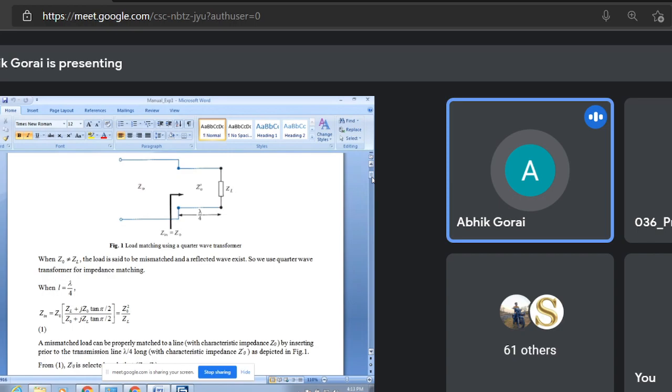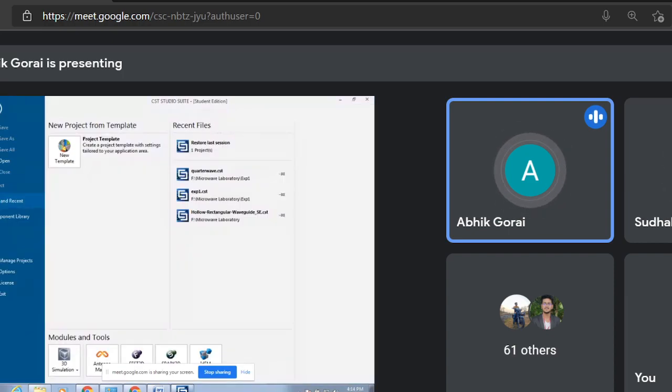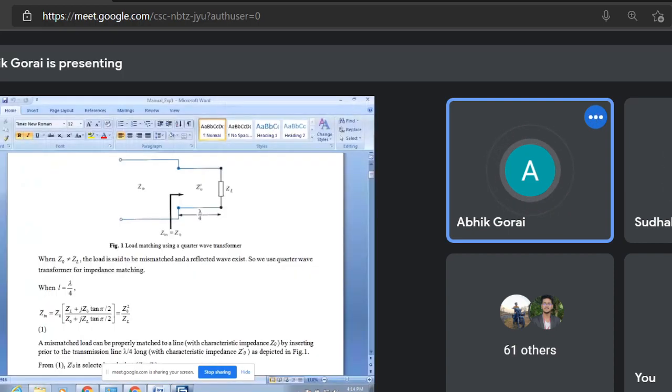In the previous class, I devoted much of the time to explaining how the S parameter will look when you have a very good matching. We will have the S parameter dB curve that lies below minus 10 dB. If it lies below minus 10 dB, definitely we will understand that yes, we have achieved the process of matching the transmission line.